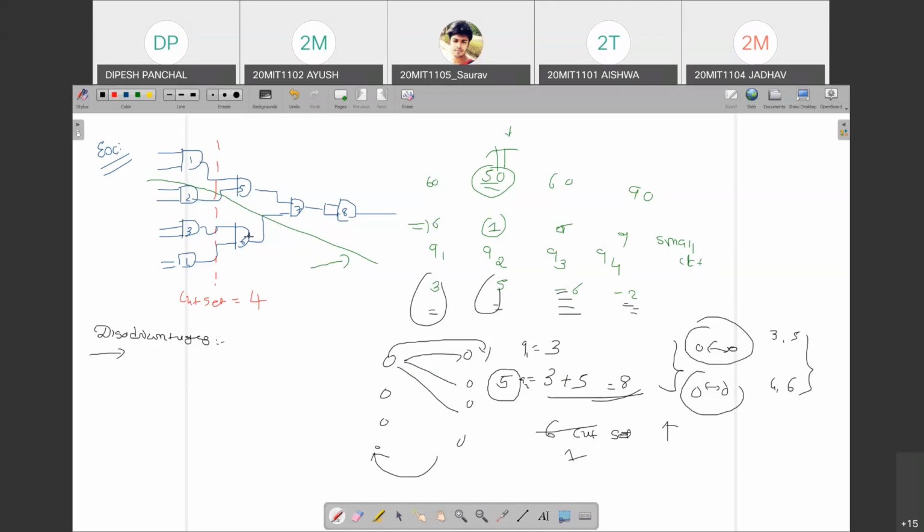If your circuit is like just 8 nodes, 8 gates are there, 10 gates are there, definitely you get the best answer, cut set, let's say 1. Here in this case it is 2. 1 is not possible, if you see. Anyhow, if you cut, 1 is not there. So let's say here the best answer is 2. So one pass gives you this result. If the circuit is too complex, your answer is 50, you have to go for the next pass. Maybe it gives 40 like this. So this swapping acts as your initial partition.